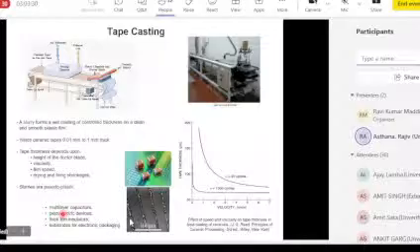So mostly you can buy feedstock from vendors, DuPont or Hagedis Corporations and others. They provide you the feedstock for whatever powders you want. And the polymer binder is a two-component polymer, a major binder and a minor binder. So during debinding, you remove the major binder and leave the minor binder intact so the part can be held together.